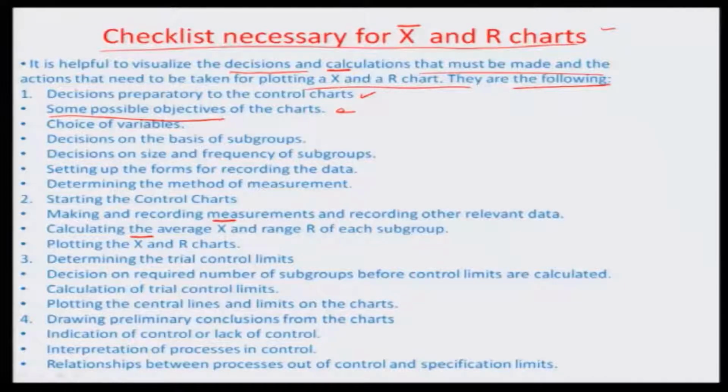That could be a function of the cutter wear at which the cutter may degrade, or the change of dimensions resulting from poor machining conditions, or maybe vibration and chatter. So, there is a requirement of plotting the measurements in that manner, with the objective of measuring the slot width of the particular milling system which is in place.